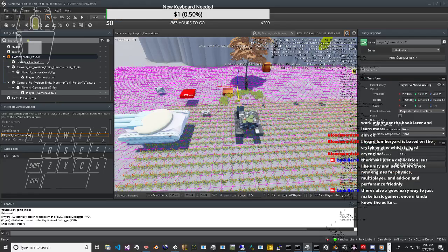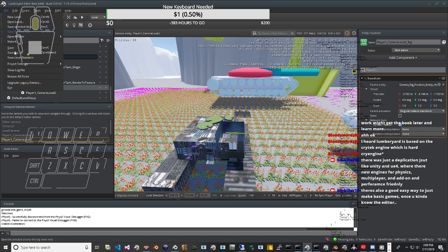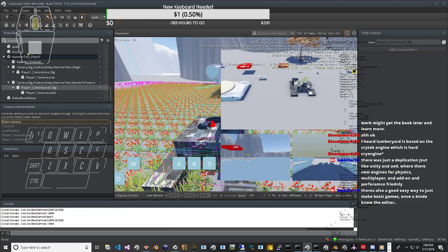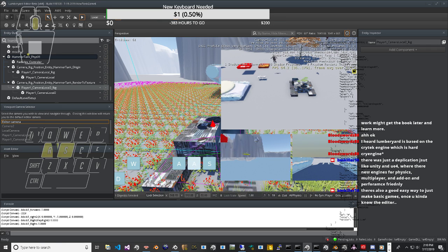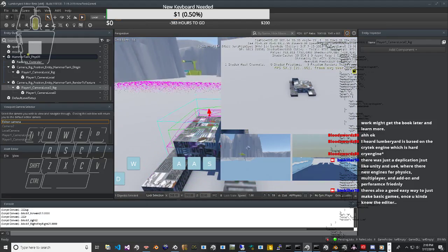As the yellow plug rolls around and approaches the contact patch from the front, it slows down in the bunched up area at the leading edge of the contact patch just forward of it. There is a bunched up area, because the tire is made up of elastic material that gets squeezed and stretched out of the contact patch and piles up ahead of the contact patch as it rolls into it from the direction of the leading edge. Eventually, the plug enters the patch, in the center of which it must move at speed relative to the hub center, that is, backwards at a speed dictated by the loaded radius and the wheel velocity. We've assumed that the plug is not slipping on the ground at the point where it has speed with respect to the hub.